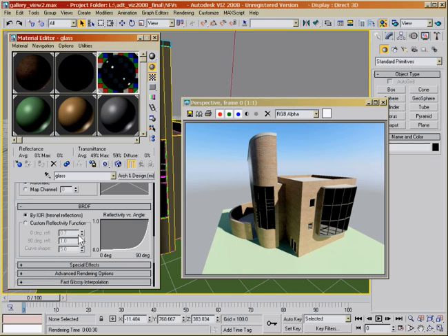By default, glass uses a Fresnel reflection, which has little reflection when looking at it perpendicularly, but a lot more when the angle of incidence starts getting very narrow. The graph shows you how the reflection changes based on the angle. If the default realistic Fresnel is not what you want, you can customize it.